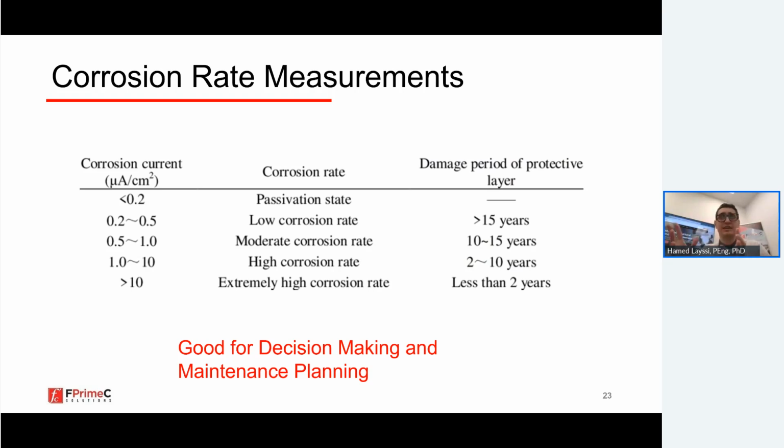All those limitations for half-cell and influencing parameters also apply to this test, and I'm going to say this test is even trickier. You really need to know what you are doing in terms of how many rebars are under your probe. The probe itself normally has a guard ring. You have to have a very good understanding of the cross-sectional area of steel under your guard ring.